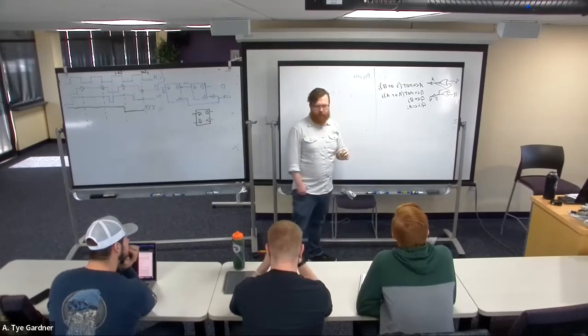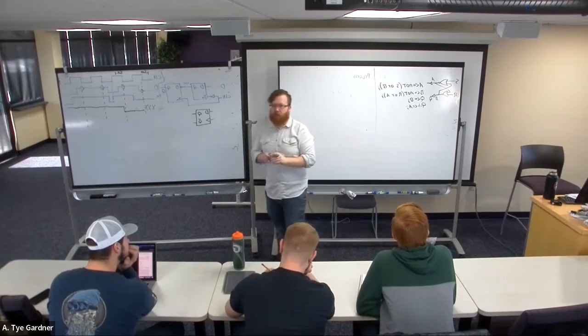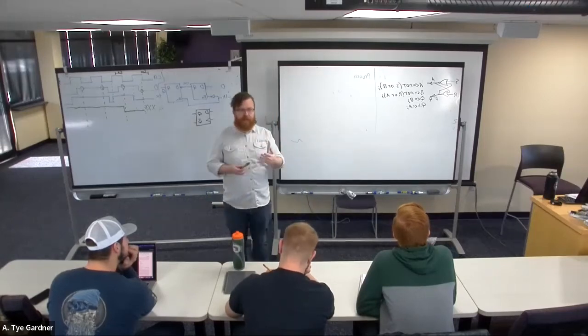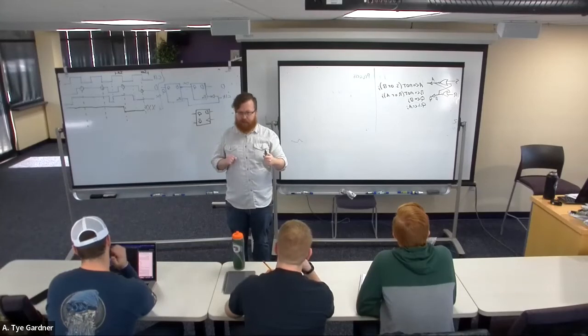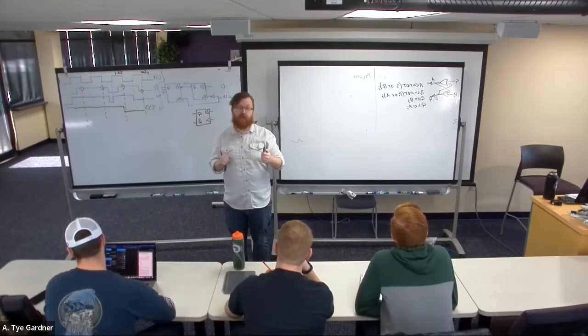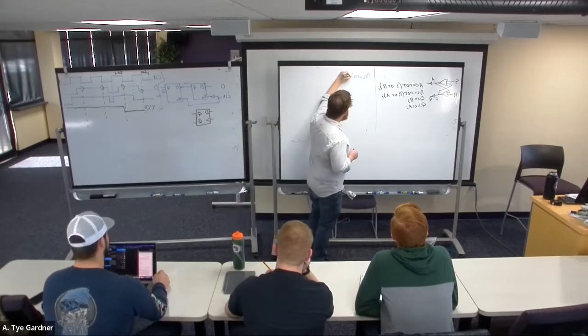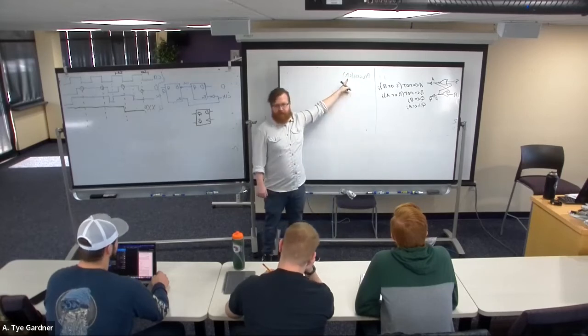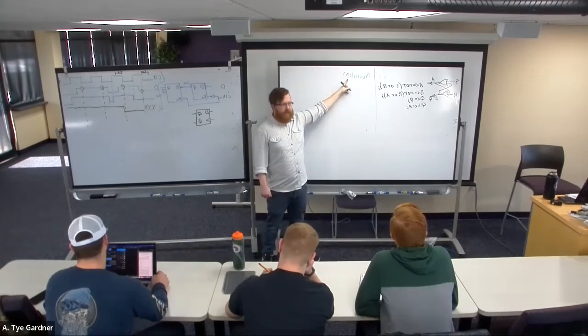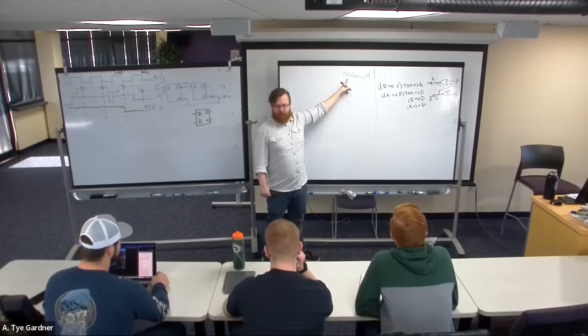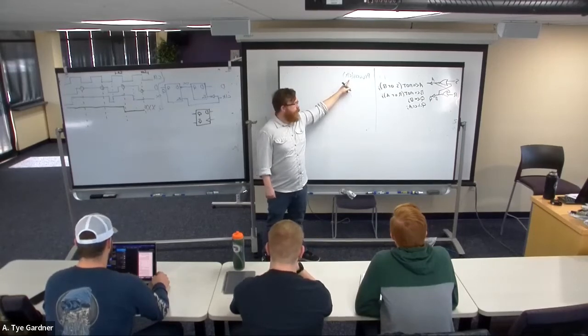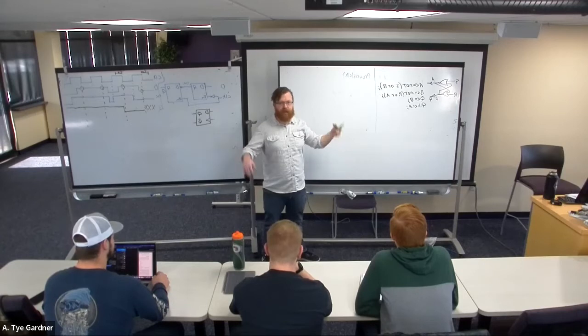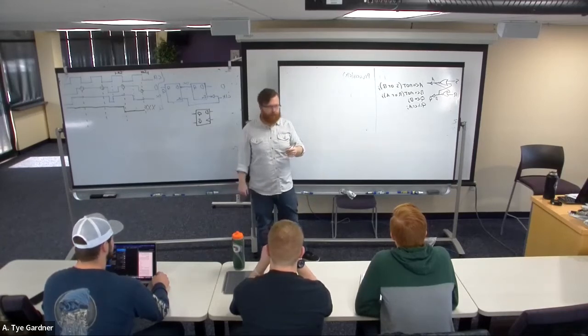I say process. However, there's a difference right off the bat, which is the process is going to react to a particular signal, in this case, the clock. So I give parentheses clock. This is called its sensitivity list. This is what signals cause the process to run. It's just going to sit there until one of those signals changes. In this case, clock is my only signal.